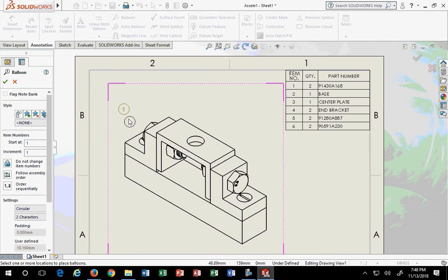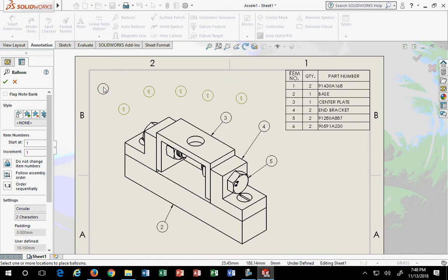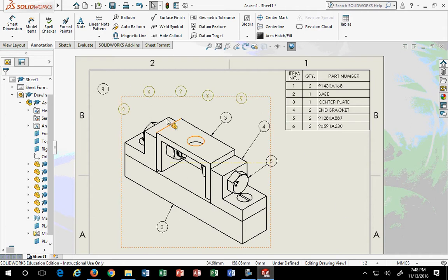Now you'll notice I dropped the balloon over there with the question mark, but if I touch something real, I won't get a question mark because it knows what it's doing. The only reason that one out there is a question mark is because I did what? Drop it out there. See that? If you drop them out here, guess what they look like? Bunch of question marks. Okay? And then you're like, why is that there? Well, that's why. If you ever wonder where the question mark ones came from, they came from you clicking. So be aware that that's how balloon works.